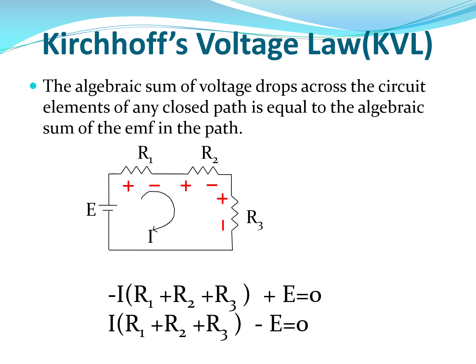You will consider the voltage drop across all the passive elements as positive, and across the source, if the current is entering the negative of the source, then the voltage will be negative. If the current is entering the positive of the source, then the voltage will be positive. So we will remember the second equation and apply it in our circuit analysis.